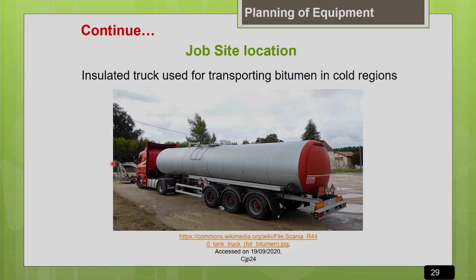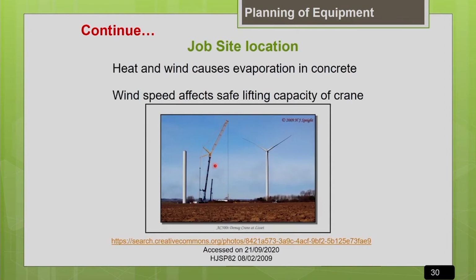Similarly, even for your ready mix concrete trucks, you can go for insulated RMC trucks, particularly in the cold weather countries, in order to maintain the working temperature. Another important thing, in the same line, you can see that heat and wind will affect the concrete performance.